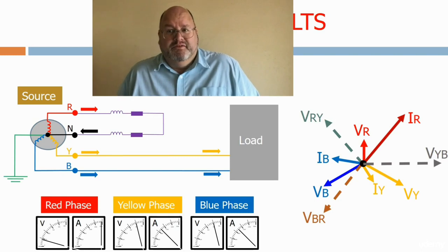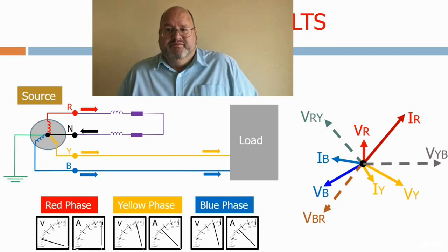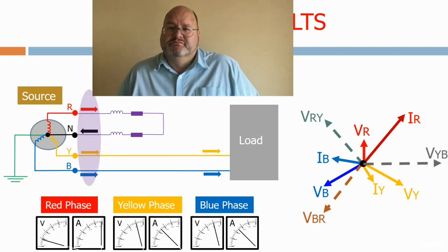The blue to yellow line voltage has not been affected and stays the same. The red to yellow and red to blue line voltages have both changed in their magnitude and angle, as the red voltage has reduced. If we now try and summate all the currents, it will still equal 0, as although the currents have increased, there is no current leaking out of the system.